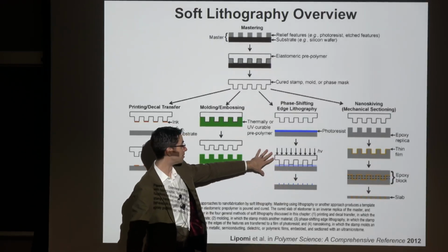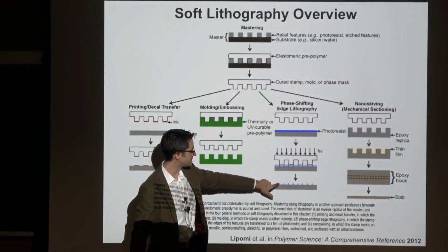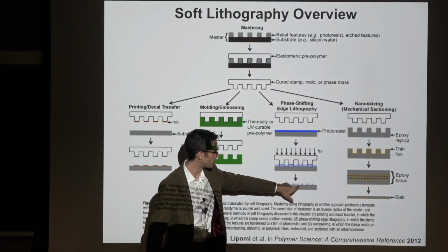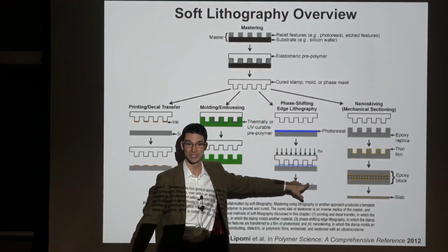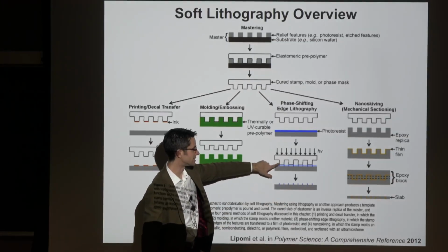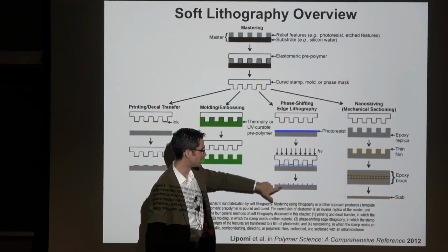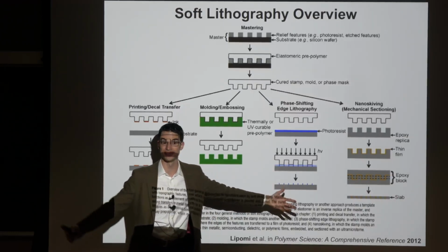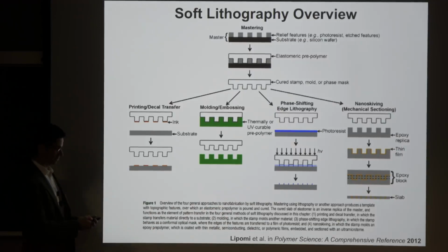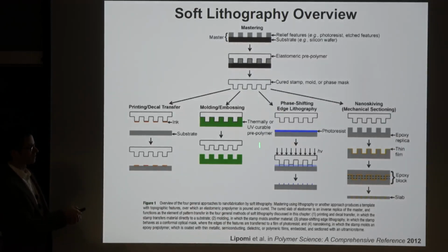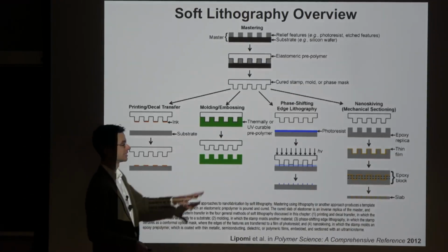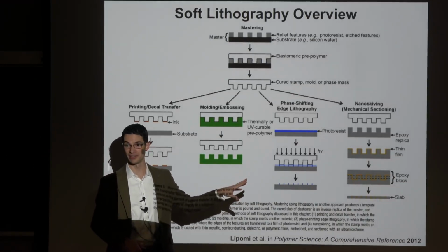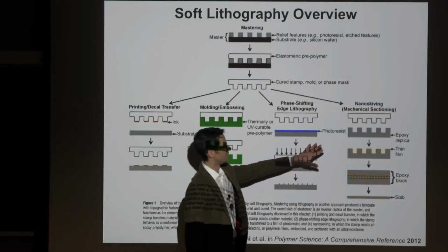Okay, and you can create images where the sidewalls were, right? So you take something with, say, a micron feature here, and you can get down to like 50 nanometers using these constructive interference patterns. This is actually the technique of phase shifting lithography that's used in the semiconductor manufacturing industry.